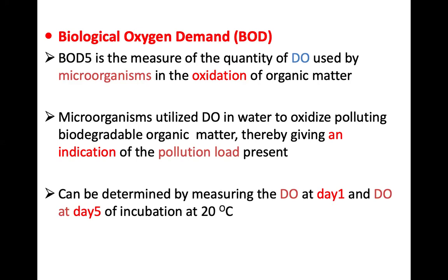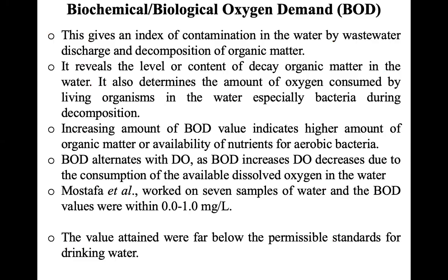This can also be measured experimentally by determining the BOD for the first day, and then you keep your samples in a dark room, and you also calculate the BOD for the fifth day, all maintained at an incubation temperature of 20 degrees Celsius. You can find the difference, and this gives you an indication of how polluted your water is.